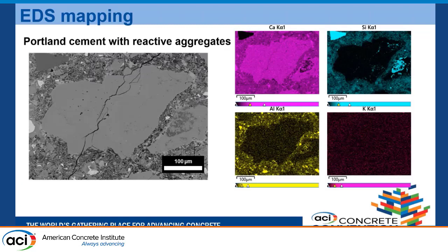It's visible in the image, and the silica on the right is visible because we use Spratt siliceous limestone, so we expect to have silica there. And aluminum, because the cement has aluminum, so we see some traces of that. But the most interesting thing would be to see traces of sodium or potassium. Here it's uniformly distributed.